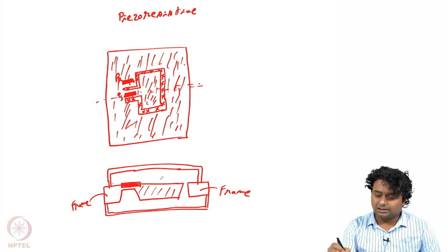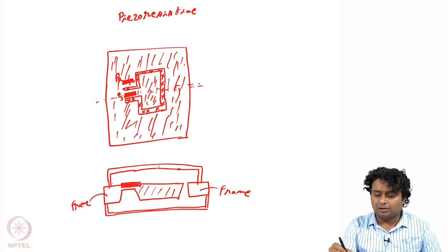As it is moving, to get rid of stiction or in-use stiction or those kinds of effects, what we can put in the top cap or bottom cap is this kind of dimples or anti-stiction tips. So even though it moves up and down, it will not get stuck to the top cap or to the bottom cap.